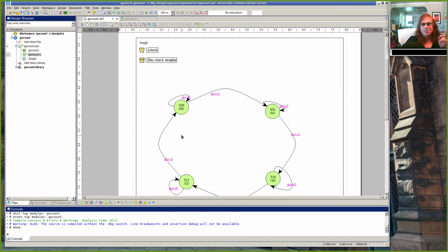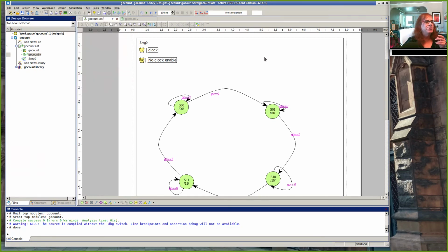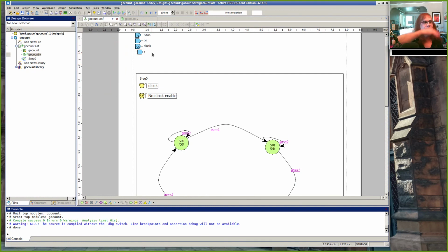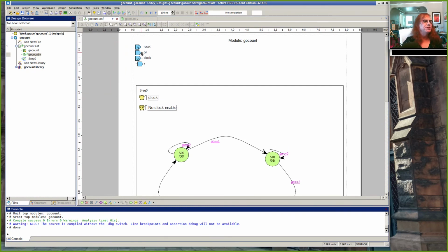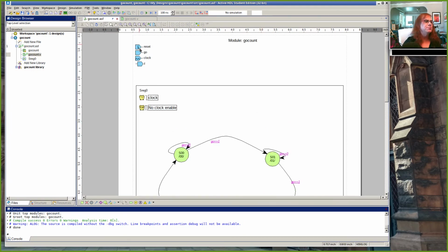So we'll compile this up and simulate it on Tuesday next week. And we don't have time to do the simulation anyway. But the effect would be, right, we'd set up the clock to be just a running pulse train. We can set up the go signal to be random and have it periodically just change from one value to another. Drive the reset for a few clock ticks in the beginning, and then when you look at the waveform, you should see the system moving from one state to another whenever go is 1, and then just staying in its current state when go is equal to 0.